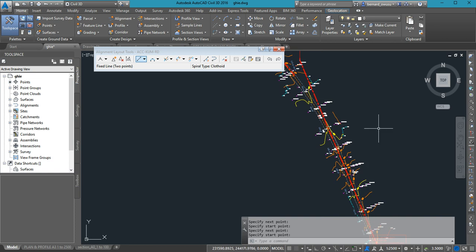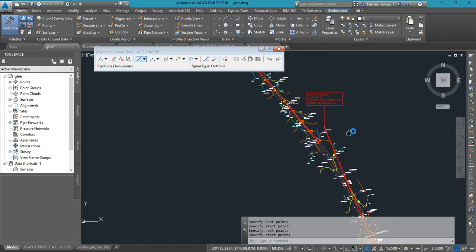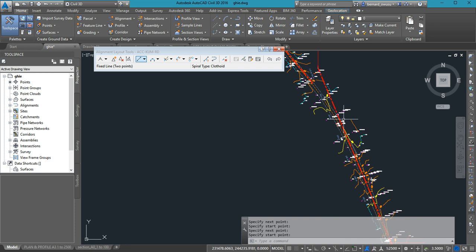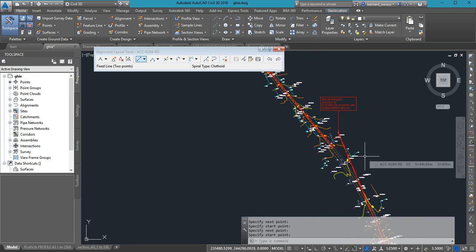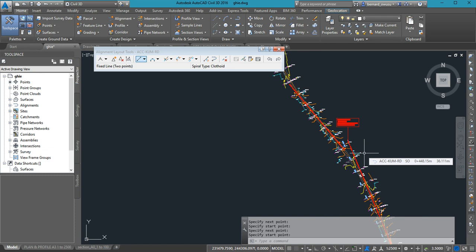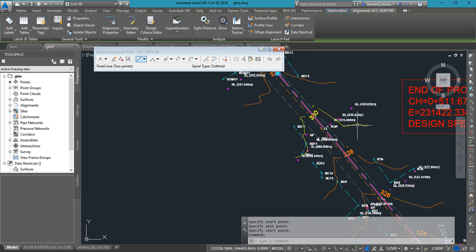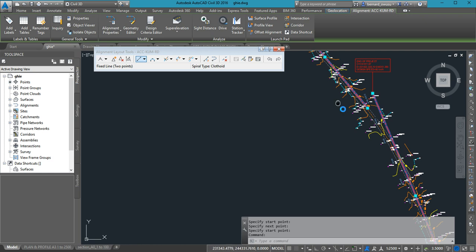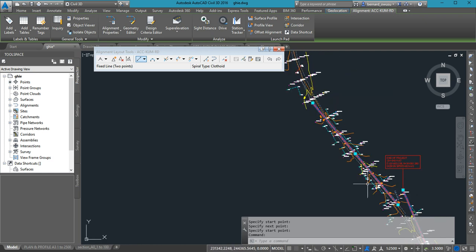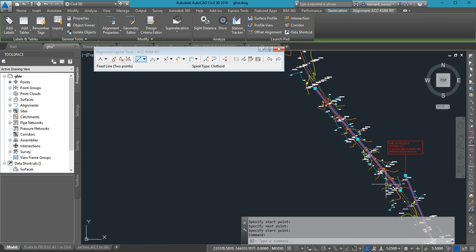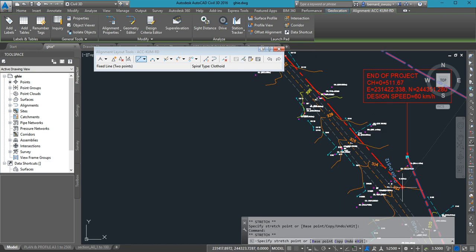So please, somebody asked a question, and please, let's all take note. Do you all have 2 tangents, or you have only 1? Now, please watch something. Assuming that this first tangent is not very perfect, you can just click on the alignment. Once it's one alignment, any one you click, it will select all. Then you can use the grip. Can you see that there are squares, 2 at the ends and 1 in the middle? You can hold any of the sides and actually change it. Do you understand? You can move it.